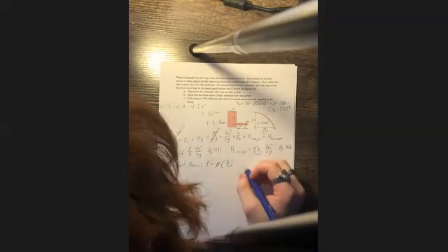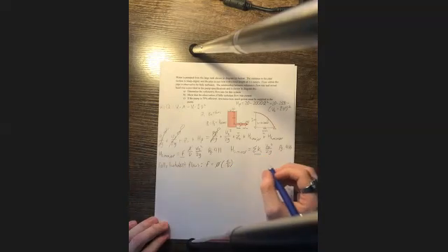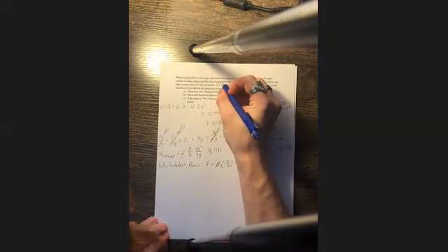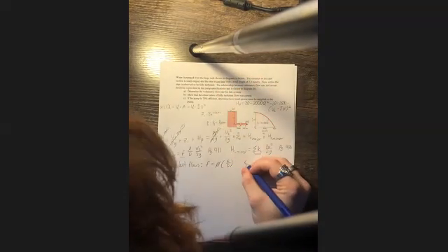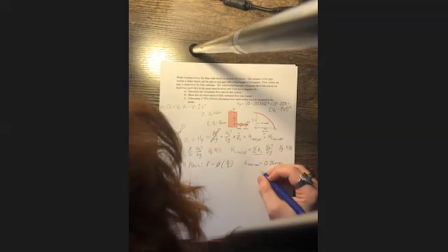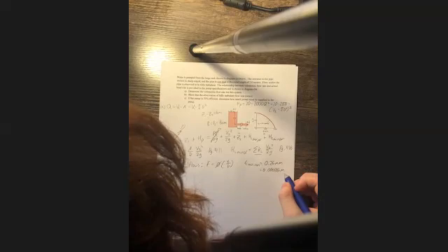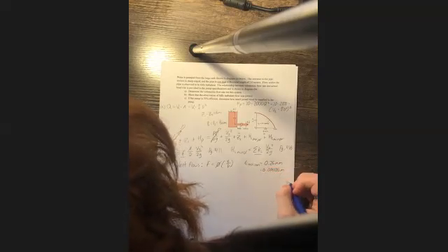So in order to solve for this, we first need to find the equivalent roughness for the pipe. And it says right here that it is cast iron, and the equivalent roughness for cast iron is 0.26 millimeters, or 0.00026 meters. Remember, there's 1,000 millimeters per meter, so I just divided by 1,000 to get this in meters. Now we want to find the equivalent roughness divided by the pipe diameter.